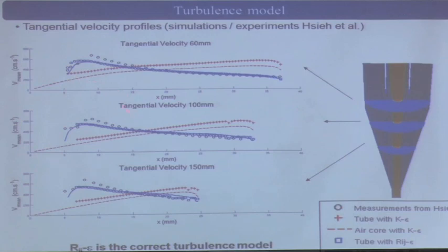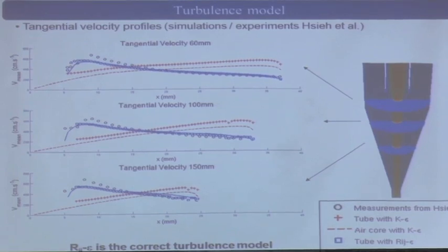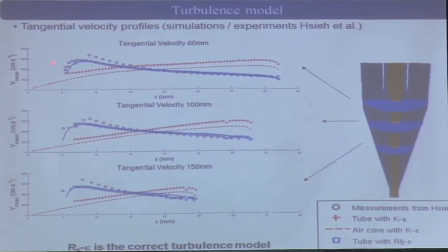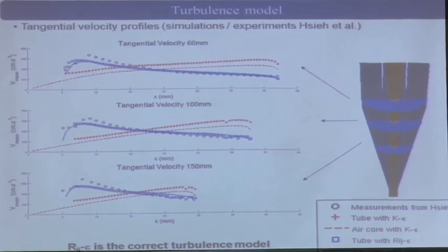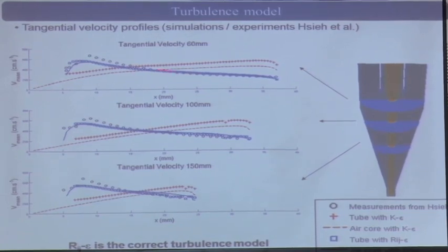And then at some point we did the validation as you proposed. So we did the validation first for water only, because it is easier. You don't have the particles, even in terms of experiments, it's easier without the particles. So we did simulation, and then you see, for example, that if you use one model, K epsilon, which is the less accurate and the less demanding in terms of resource, you see that the red line are very far from the dots, which are the experiments.